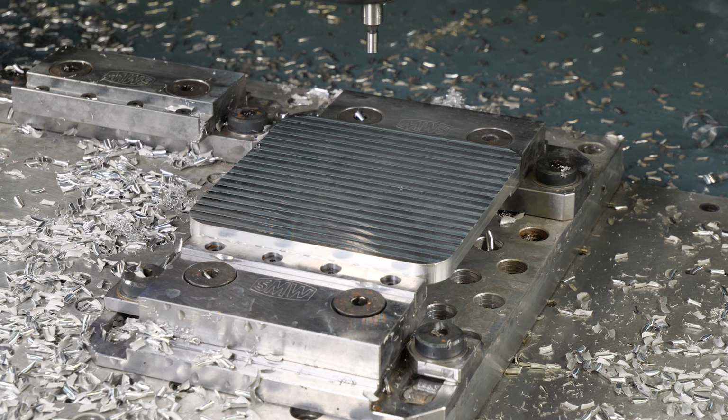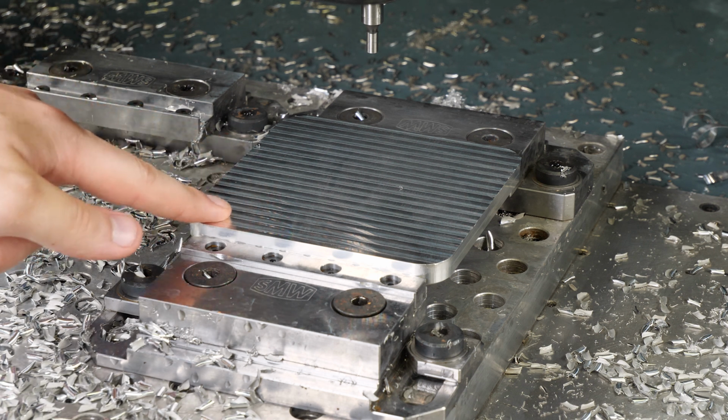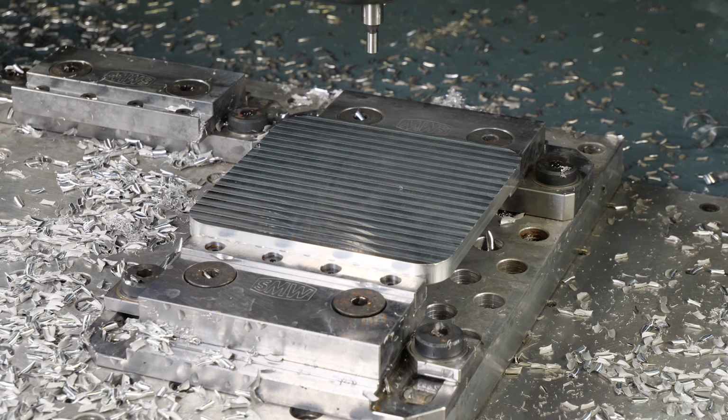Alright, so we just got done mowing off the top of our part. Took off nearly 200 thou there, and so now we're left with a nice clean finish, good looking lines, everything looks good. So the next thing we've got to do now is touch off our part again. See, what we did is we touched off our stock earlier, and as we know, stock's not perfect material, it has some slight bends and variations to it.